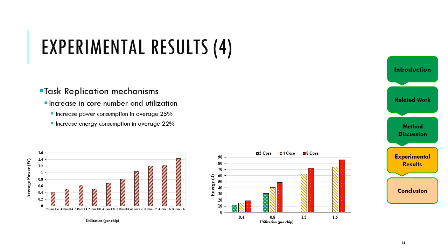The homogeneous system is considered to evaluate the task replication method. This is because we want to run the primary and replicas equally, and there is no need to synchronize tasks and replicas. We evaluated the impact of frequency and the minimum number of replicas on energy consumption by increasing utilization and by increasing the number of cores from 2 to 8 under a given reliability target.